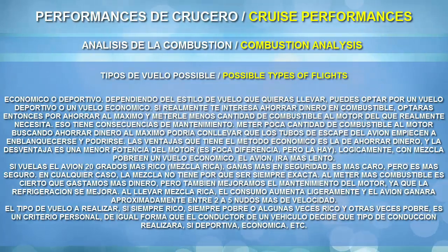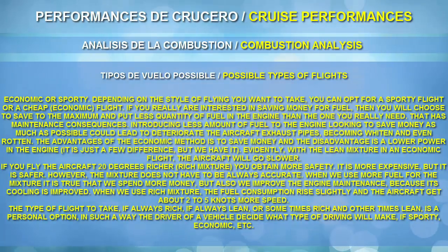So when you have to decide if you fly rich or lean, I will say that you need to fly rich always, except if you have certain meteorological conditions in which you see you are short of fuel, and perhaps you are not very sure about the quantity of fuel you have, or you have a technical problem in a fuel tank and you're losing fuel, and you need more nautical miles. You need to extend your operational range, and then in that case you have to make sure to get extra nautical miles when you're flying. So finally you will be the one that will decide if you want to fly lean or want to fly rich. But what is recommended?